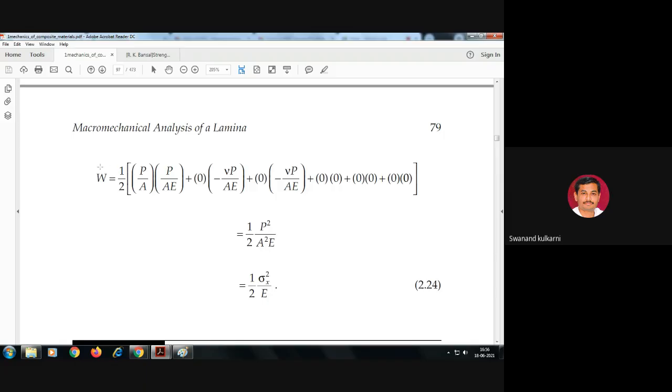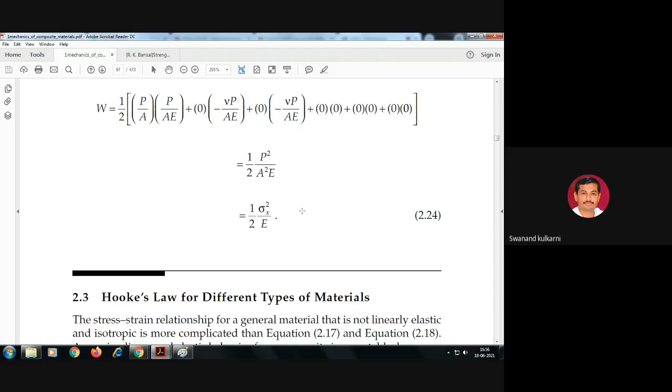Now if we multiply this and get the value of the strain energy, here we are getting 1 of sigma square V upon 2E, the equation of strain energy we have already formed, because in analysis of mechanical elements we studied strain energy and impact loading, and whatever assumptions we made and equations we formed at that time, that equation was sigma square V upon 2E.